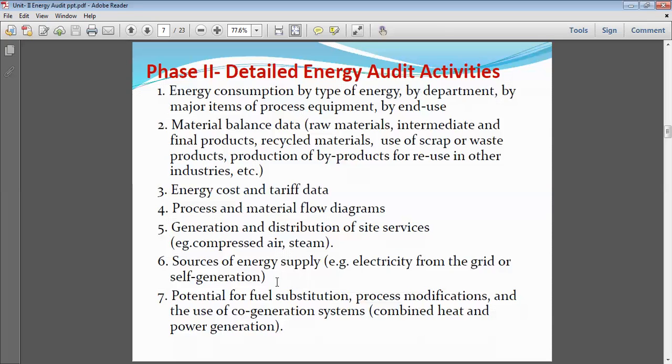So now it is not necessary to run this effluent treatment plant in the daytime. We can shift it into the night time, because at night the electric energy unit rate is smaller. Similarly, the water pumping system we can shift to the night time, isn't it? No doubt our process and our office, we cannot shift into night time. So whatever less priority feeders there are, we can shift into the night time, and this can be understood by the energy tariff or what kind of source of supply there is.